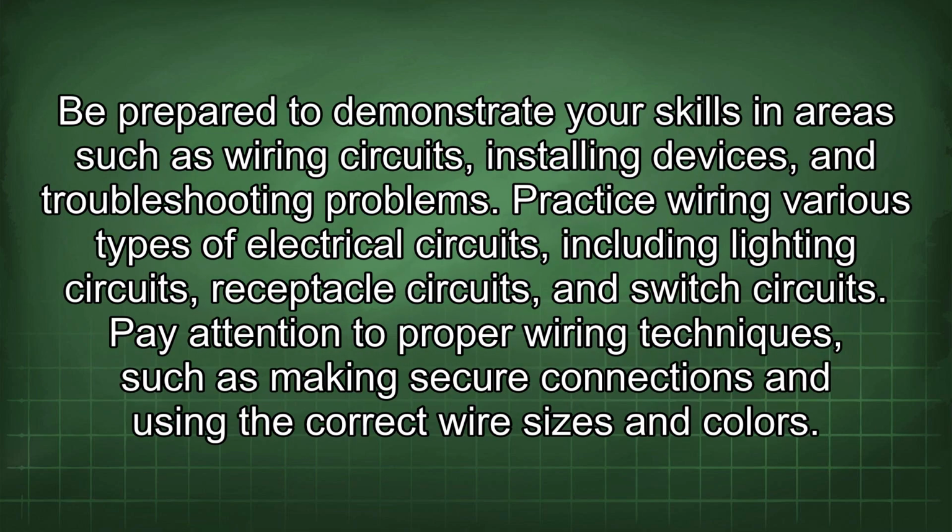Be prepared to demonstrate your skills in areas such as wiring circuits, installing devices, and troubleshooting problems. Practice wiring various types of electrical circuits, including lighting circuits, receptacle circuits, and switch circuits. Pay attention to proper wiring techniques, such as making secure connections and using the correct wire sizes and colors.